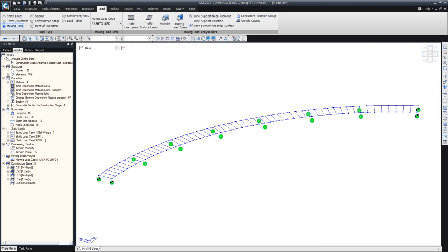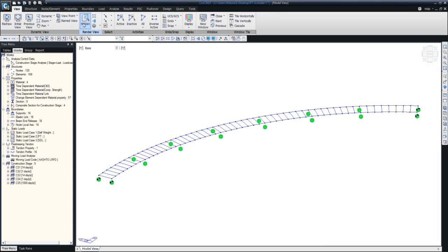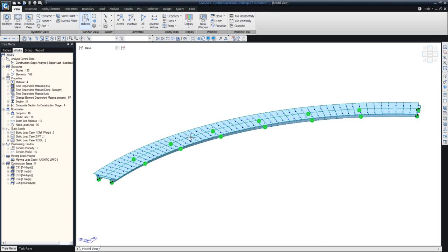We call it a dummy element because it is not really something in the physical world that you can see. It is just to replicate the transverse stiffness of the deck. So when we are saying we have the lid slab and the deck slab in the picture, we are saying that their longitudinal stiffness is taken care of, and the transverse stiffness of the deck is being represented by a transverse member.